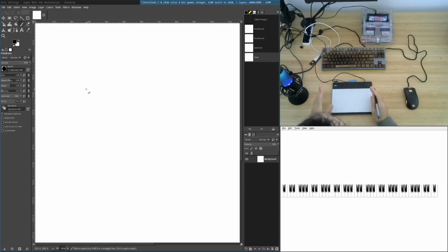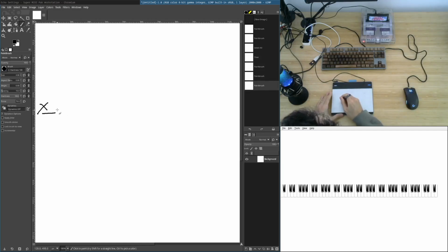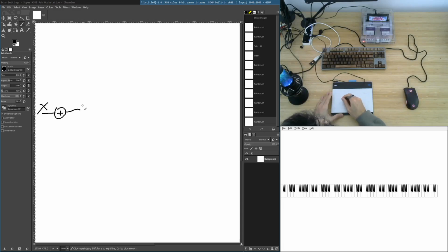Okay, so let me draw out the filter section of the SNES to give you guys a better idea of what's going on. It starts out with the signal coming in here, and it's added to something. We're not going to show what it's added to quite yet. Then it passes through a delay by 1 unit of time.